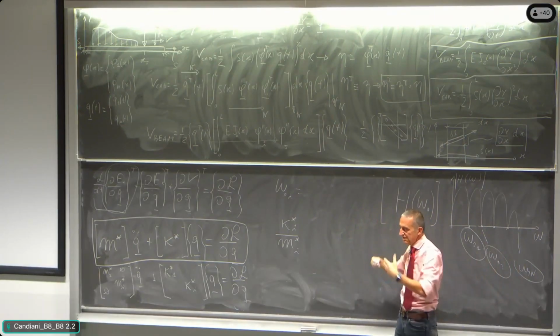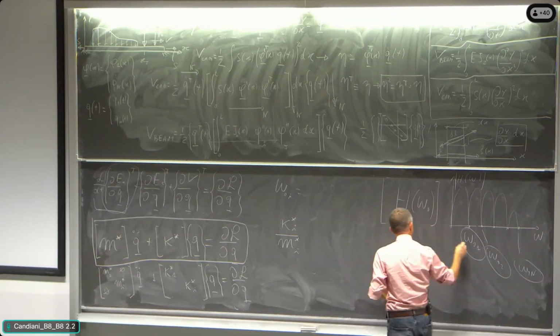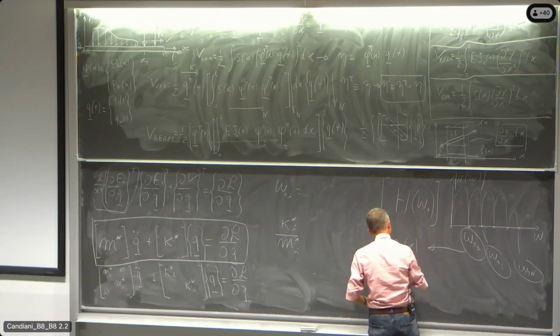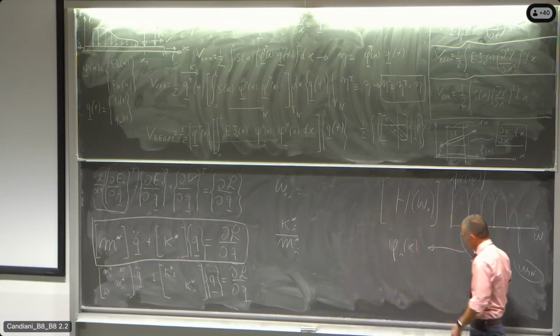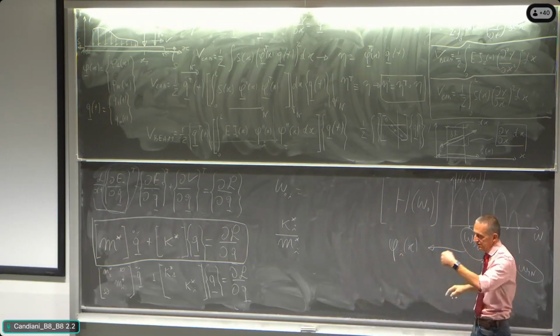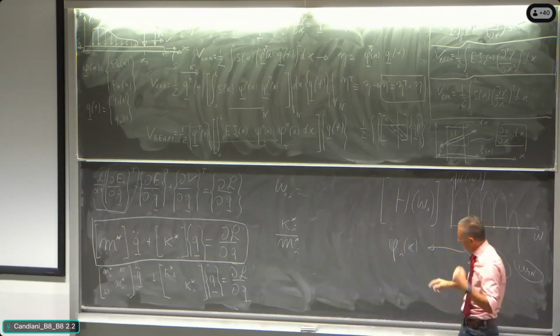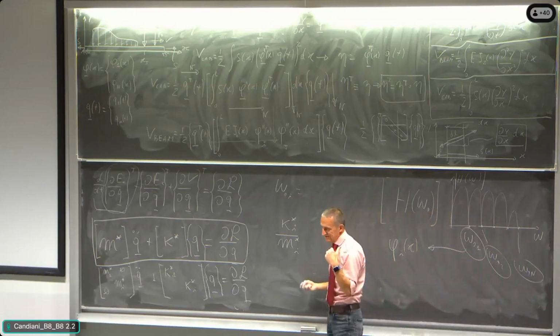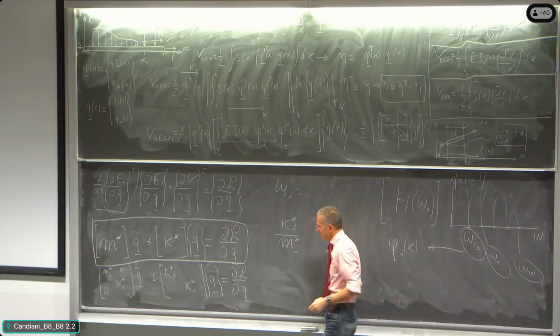So the link among the two procedures is that from here you are calculating phi i function of x that is dependent on those numbers. With the omega 0 you are calculating gamma, with the gamma you are calculating the shape. And so there is a link: the link is the modal shape, the shape of the modes.